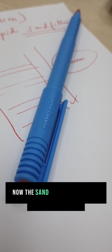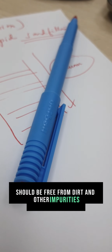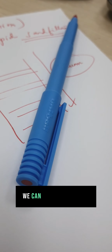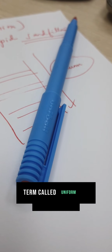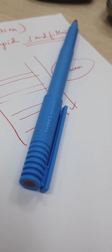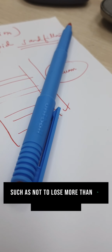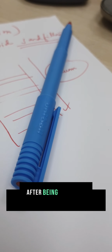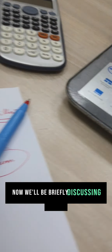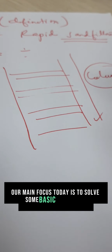Now the sand that we are going to use here should be free from dirt and other impurities, and should be uniform in nature and size, which we can find by the uniformity coefficient, which is the ratio of d60 by d10, and it should be hard and resistant. It should not lose more than 5% of its weight after being placed in hydrochloric acid for 24 hours. Now we will briefly discuss the filter theory. Our main focus today is to solve some basic numericals.